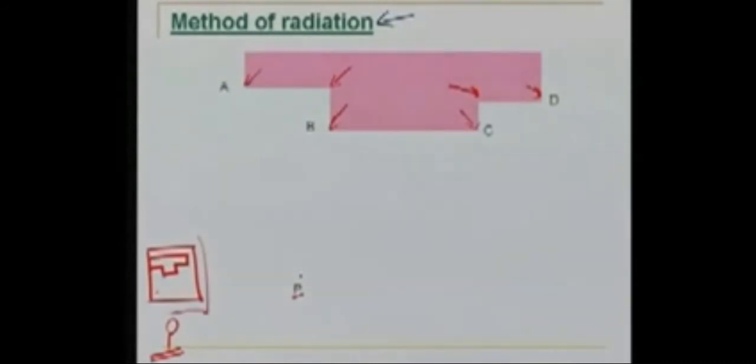So if we compare the geometry of this building and this point, over here the building and the point should be somewhere here. So once we bring our plane table, I will set my plane table on point P using the plumbing fork.